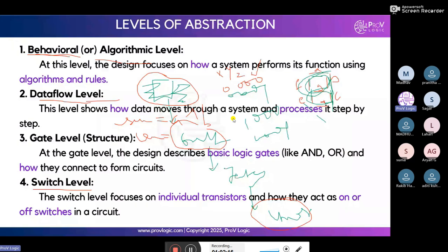Gate level netlist, in the sense, for the full adder we have the gates, like one XOR gate here. Yesterday I showed you this while doing the synthesis. That program is gate level, which means we write the program using gate primitives. Next is switch level. Switch level means we write the program using CMOS transistors. So these are the 4 levels of modeling. Did you get the point?